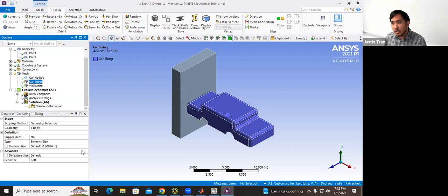When you're talking about the accuracy of your mesh, you have a couple of sliders. One is that you can change the order of the elements, and going from linear to quadratic is going to make your simulation more accurate. But another way to get accuracy is just to mesh the hell out of it: make your element size so small that you have so many elements. When you're forced to have linear elements in a situation like this, you really want to make your element size small enough to get an accurate result.